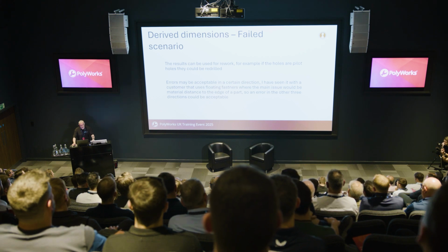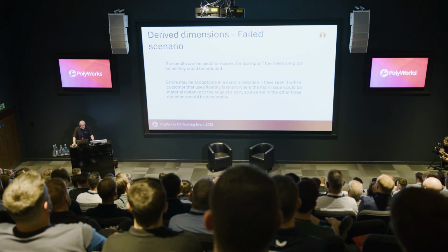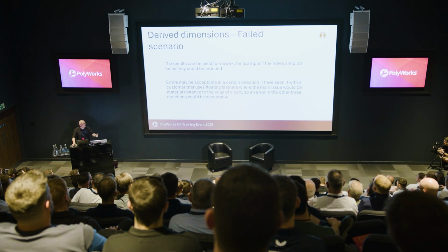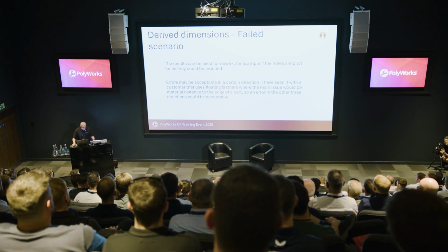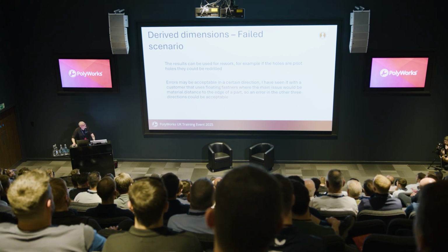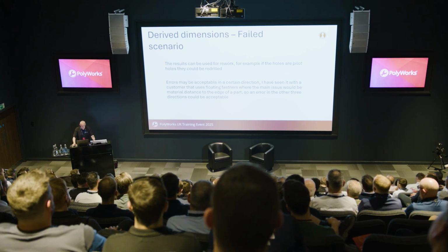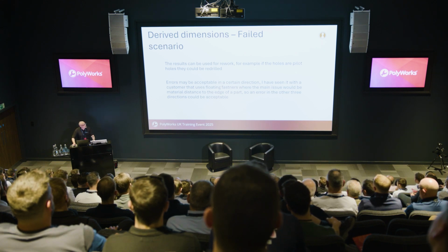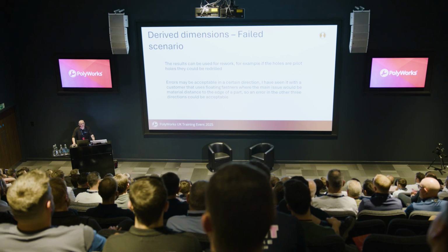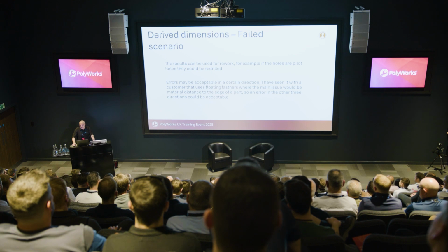So, in the failed scenario, what we'll be able to do: if they are pilot holes, we could re-drill before we put the holes in. And then, again, this is the example that the two guys in the audience will know about. Errors might be acceptable in a certain direction. So, the customer I'm talking about had floating fasteners, and if they all moved in the same direction, it could be acceptable. And then you had to watch they weren't coming too close to the edge of the part. So, movements in a particular direction might be acceptable, which you wouldn't be able to tell directly from the GD&T for positional tolerance.